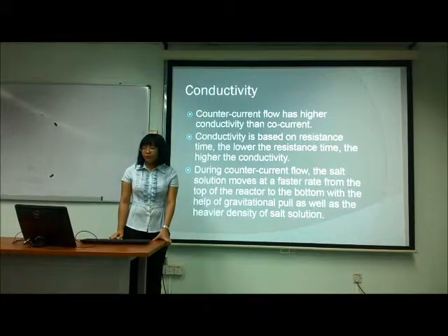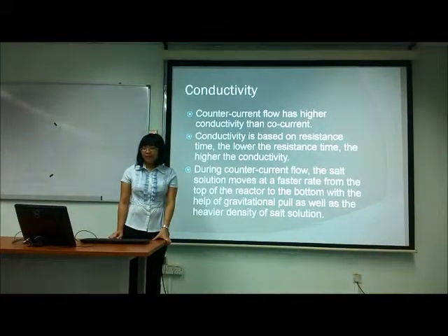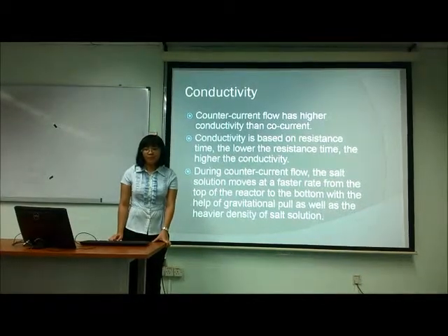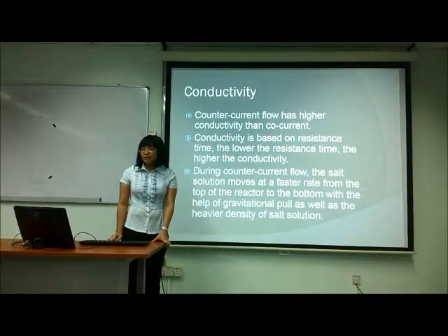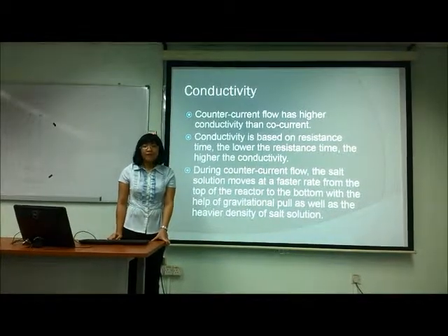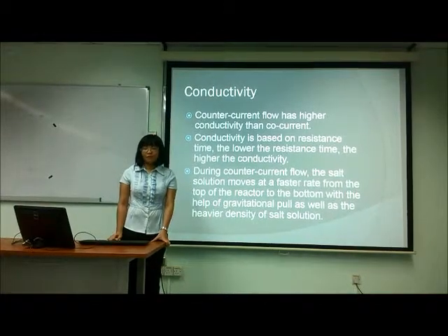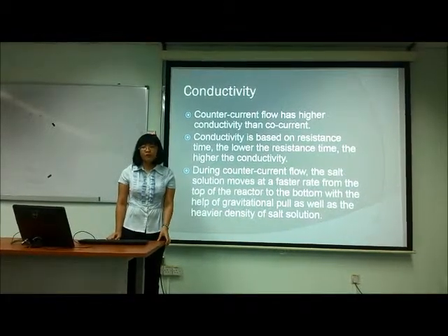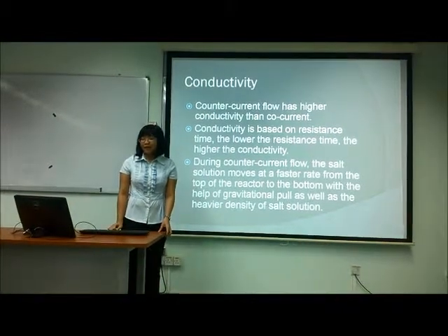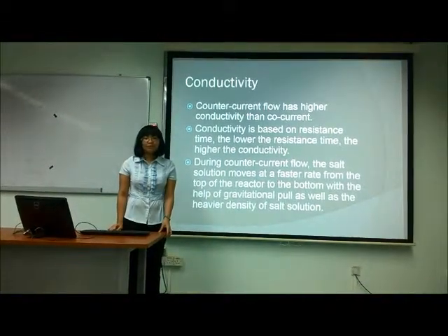Now, conductivity is based on residence time. The lower the residence time, the higher the conductivity obtained. We can see that actually counter current flow has a higher conductivity compared to co-current. This is because in counter current flow, the salt solution moves at a faster rate from the top of the reactor to the bottom. It is also helped by gravitational pull as well as the heavier density of the salt solution.